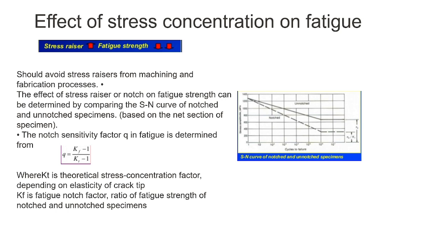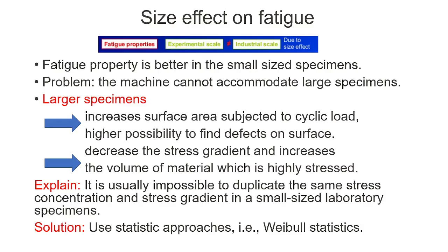We should avoid stress raisers from machining and fabrication processes. As the stress raiser increases, the fatigue strength decreases. That's what we have inferred from the previous understanding. Now the size effect: fatigue properties are better in small size specimens.